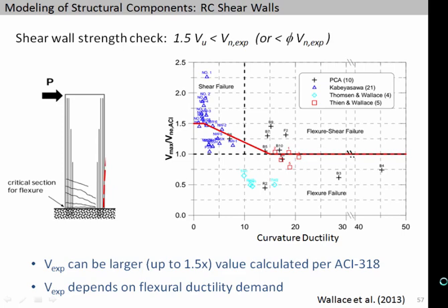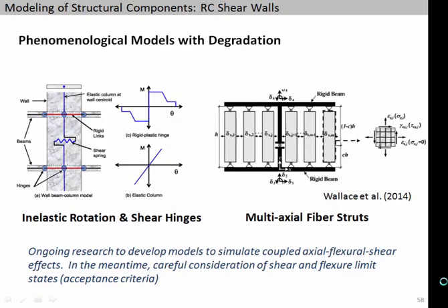If you think of your actual wall, sometimes the place where the shear might be largest, down at the base of the wall, is also where you're hinging the most. So if you start to take advantage of some of this added shear strength based on tests, be aware of this coupling. When we say it's strength controlled, we don't always couple the fact that the shear strength we have is affected by rotation. It's kind of a separate check: what's the strain of the rebar? And then let's check the strength of the wall. But the two have some coupling, and there are data like these available to help us sort through that. There's continuing research to develop better models that might, in these fiber wall models, actually combine the shear and axial effects.